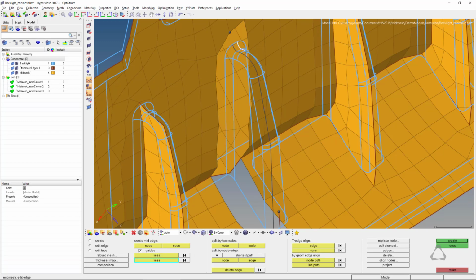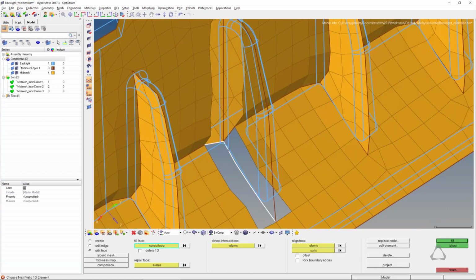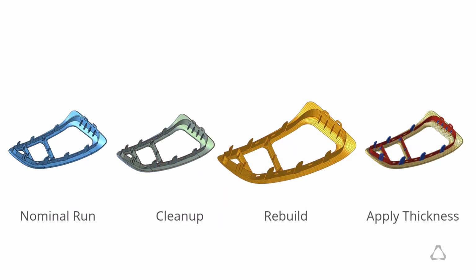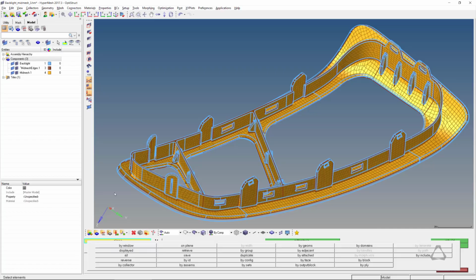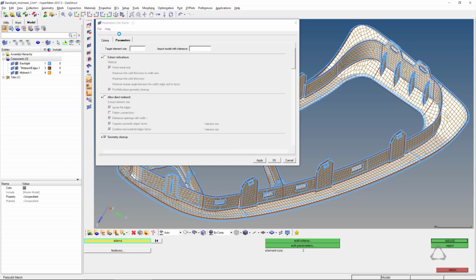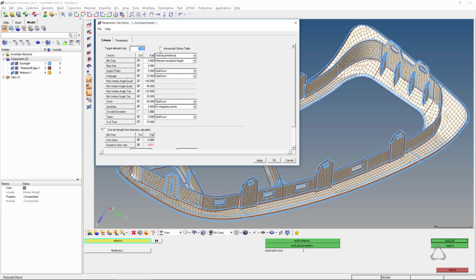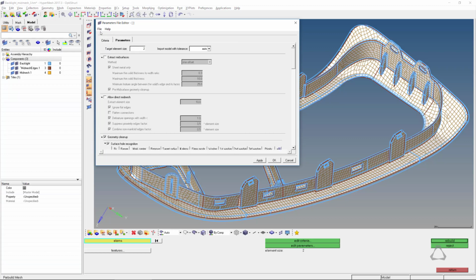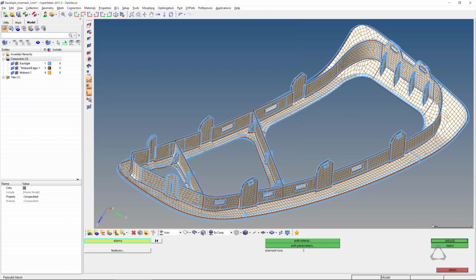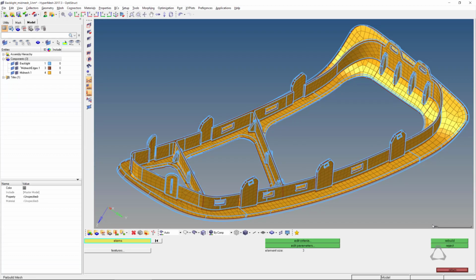Once the edges are defined, missing surfaces can be filled, sometimes by one mouse click, or an entire area of mesh can be repaired at once. After the previous step, it's now time to generate the final mesh. The process is based on common criteria and parameter files and requires only the element selection as input.